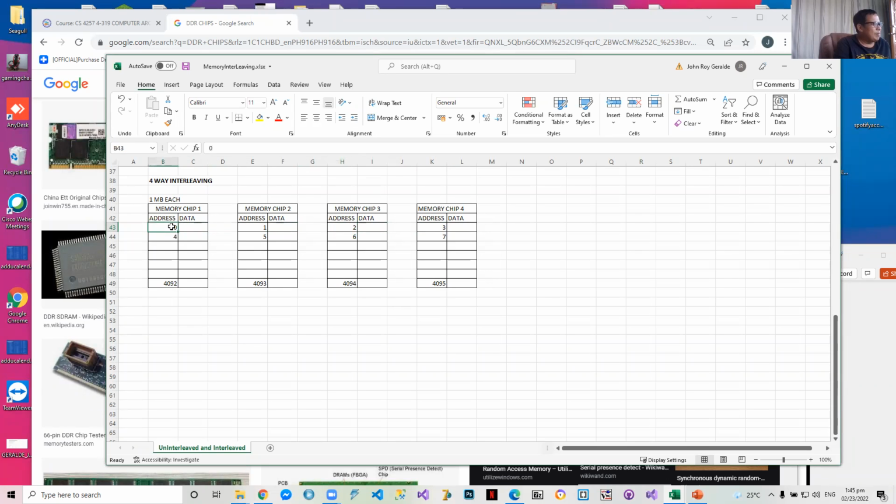So which means that when memory 1 is being executed, or in half the phase of the memory cycle of chip 1, all the other 3 can now advance the read, so that there are 4 bytes being read in advance. So the next time around, when there's an address of 4, it's going to be placed on the next vacant space in the pipeline, so that when the next address is requested, the CPU doesn't have to go fetch it directly from memory, which will be very fast.